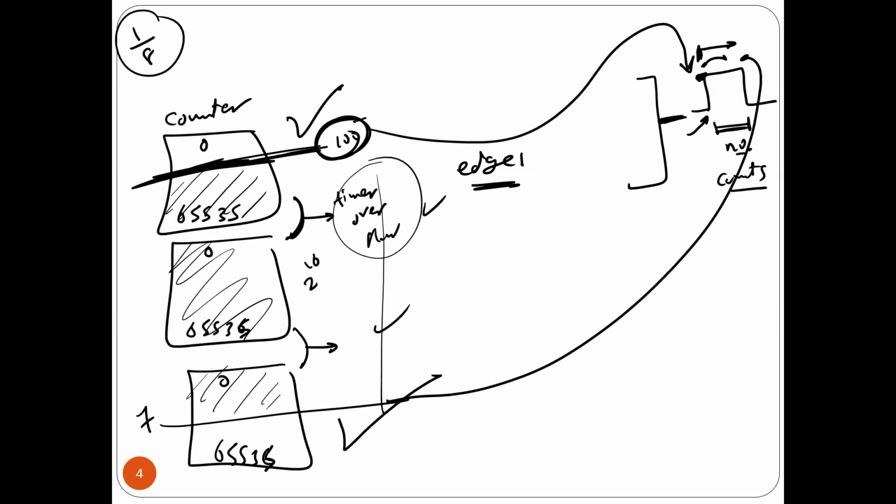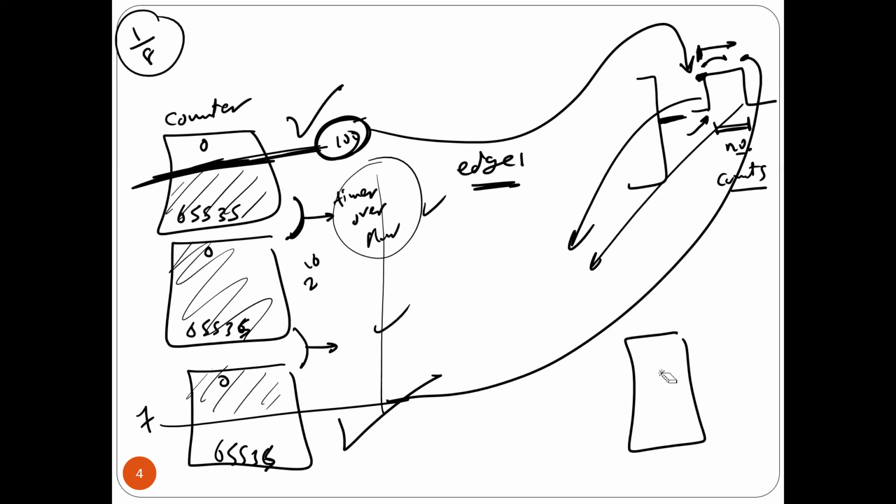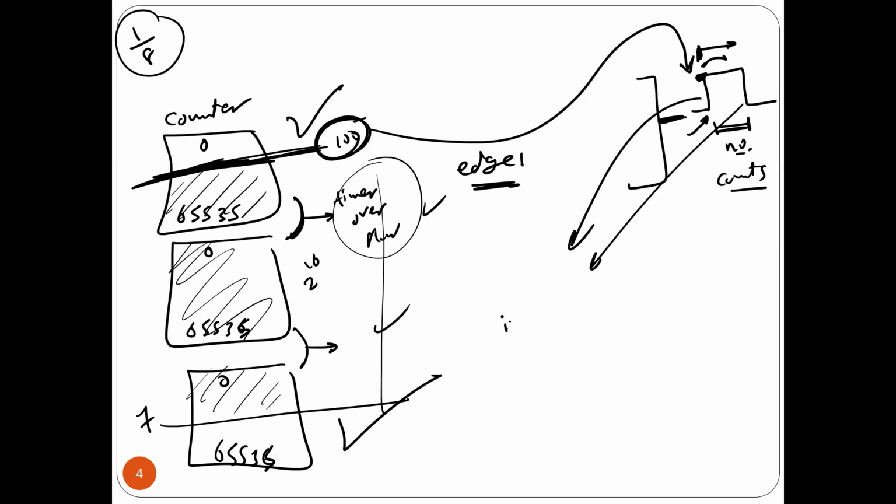Okay, remember, we're going to have 1 interrupt here and another interrupt here, so we're going to have 2 interrupts. That's why here in the interrupt subroutine, as you will see right now, I have to know. So in order to measure, I need 2 interrupts. That's it. After the 2 interrupts, I already have the numbers. I'm going to use the numbers to do the calculation and get the number of counts. Is that okay? So that's why, as you see right now, I'm going to count interrupt number 1, interrupt number 2. Okay. So what should happen is that, look here, guys, in interrupt 1, I'm going to have a variable. This variable should count.